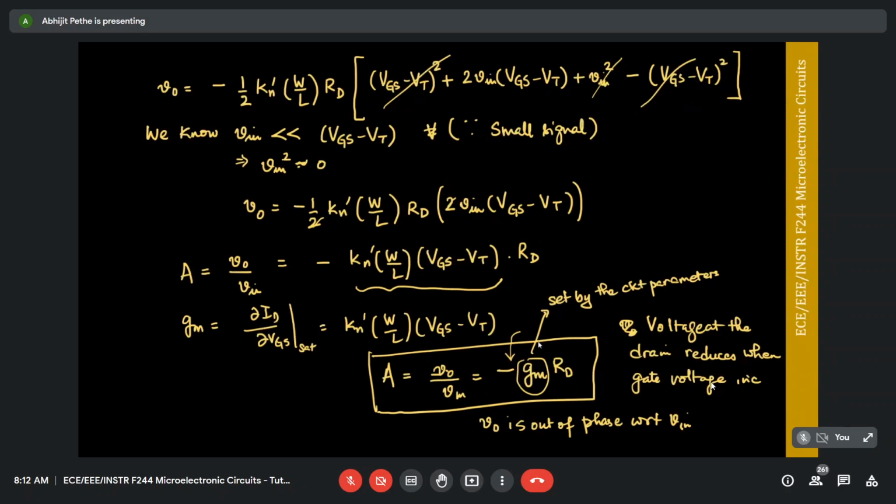Though again, remember, when you do design of amplifiers, when you're doing design of analog circuits, you have to worry about two things. When you have to design for a particular gain, the gain depends on the DC biasing of the circuit. Hence, biasing of the circuit will be very important, and we'll spend a lot of time understanding different biasing techniques, figuring out which is a better biasing technique, and looking at ways to quantify biasing techniques. How do we ensure that we are biasing the circuit correctly so that this gain remains stable?